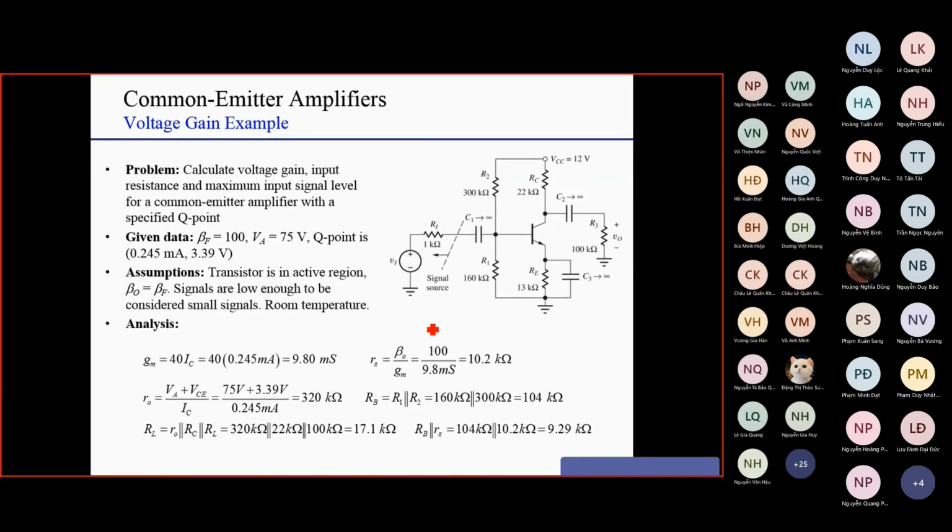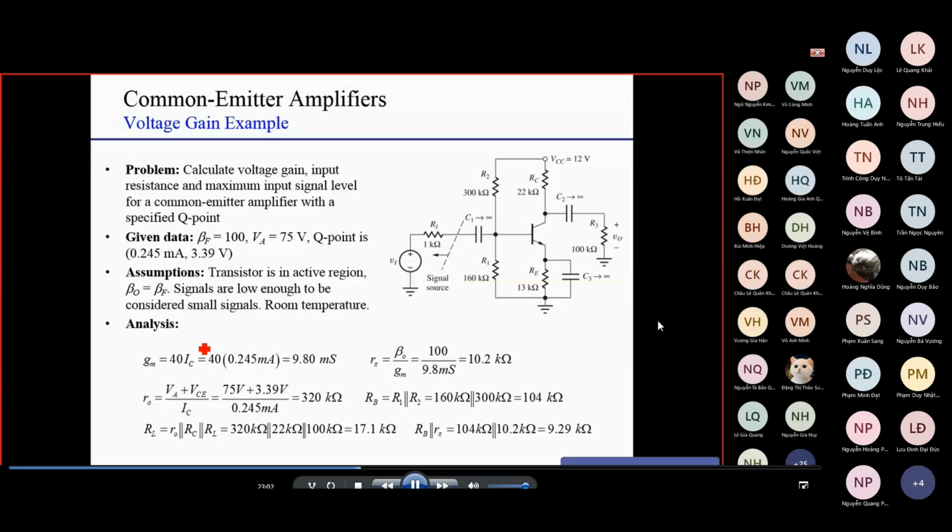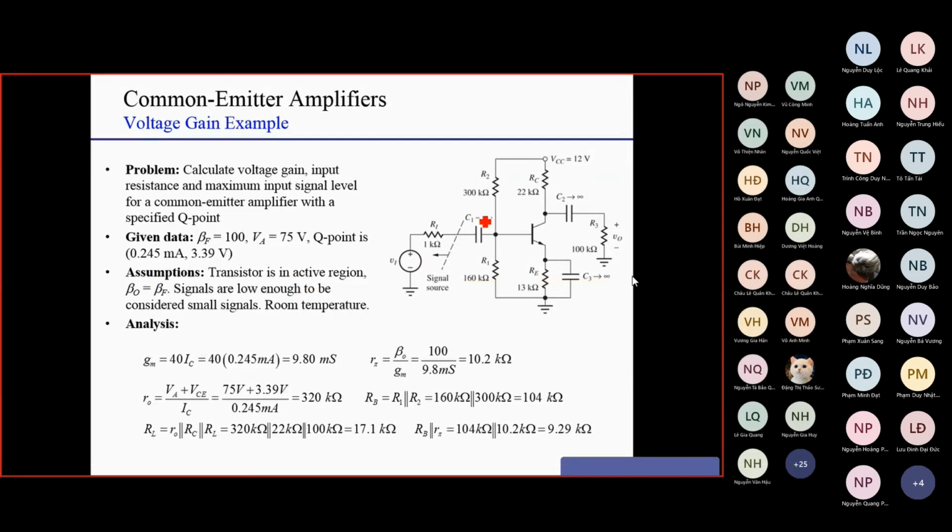So let's take an example here before we stop. We have a real circuit here, we just replace the numbers. So the Q point: from the four-resistor biasing network here, we can calculate the Q point, the current IC and VCE. It's not really optimal. You can see here the VCC is 12 volts and VCE is only 3.2 volts. It's not the midpoint.